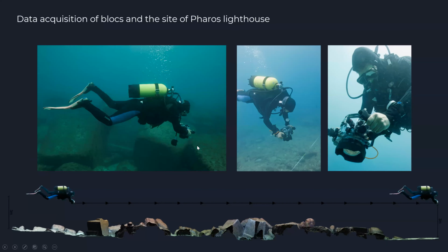The data acquisition on the site exactly simulates drone imagery. Of course, most maritime archaeologists and divers know how to take photographs under the water. As you can see, the visibility is not in great shape, so we have to be very close to the site. And the site, like I mentioned, is around 15,000 square meters under the water, which is very challenging for us. So we decided to divide the site, each season or each year, piece by piece, by putting down a grid and starting to capture the photographs.